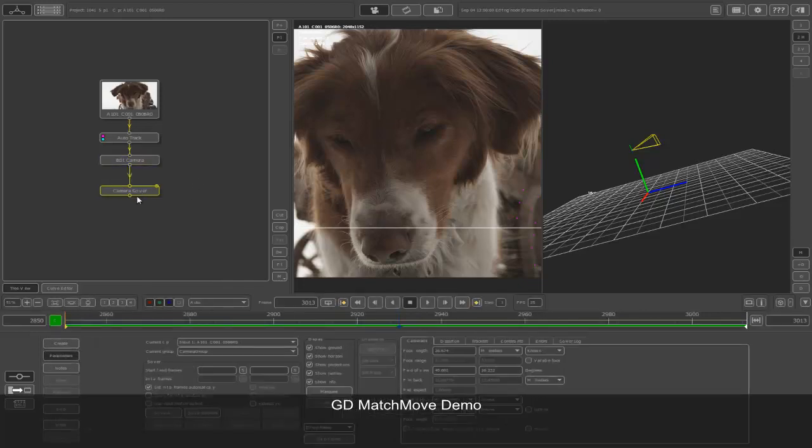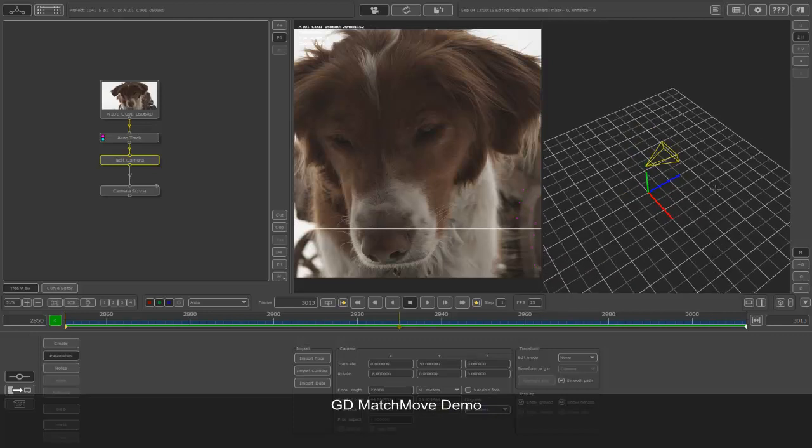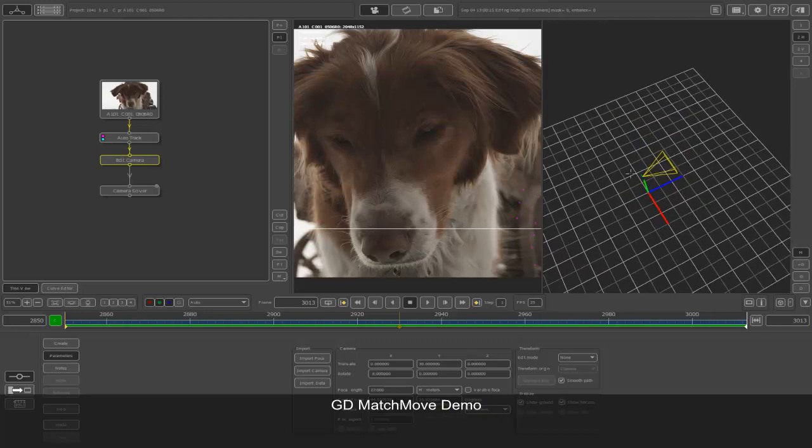So as soon as we bring in a camera solver, you can see the focal length parameter is over here, which we did not set in our edit cam. So let's go back to edit cam. The focal length is supposed to be 27, not 26.6. Set it to 27, enter. We plug that in, and you can immediately see the grids moved and the focal length has changed for the cam. The focal length is basically given by the angle of the camera.